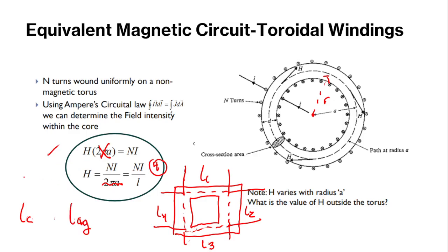When you do the full thing, L is equal to L_c plus L_g, so you just have to make sure to subtract it, because they're two separate legs individually. But when you do the main calculation for the lengths, it would be one total leg, since the flux passes through the air gap at both ends.